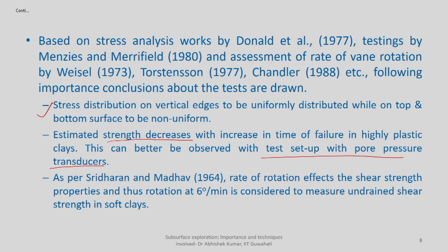That will give some additional component to the torque you are measuring, and that is why you will end up overestimating or underestimating the final shear strength, because you are not quantifying the pore pressure induced with respect to the rate of rotation. So, at the end it will end up underestimating the shear strength of the material.